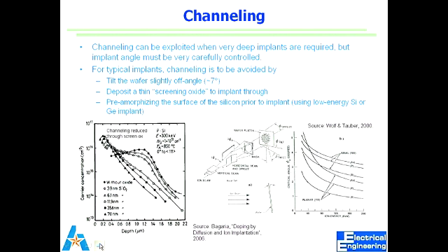So in this case, we see there's channeling through screen oxide. So we have an oxide at the top and we see how deep it goes. So this is for phosphorus, P-type silicon. No, it's phosphorus, it's not P-type. We can go down to 12 micron, which is really deep. For a device point, it's really deep. So we can use channeling to our advantage.